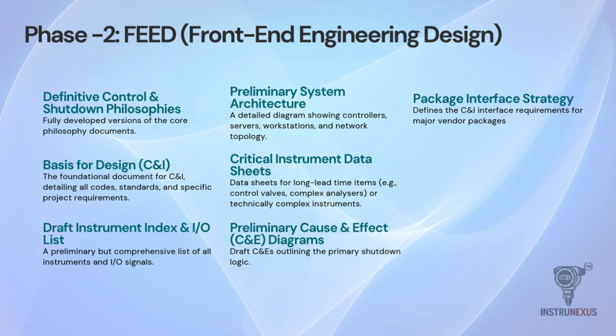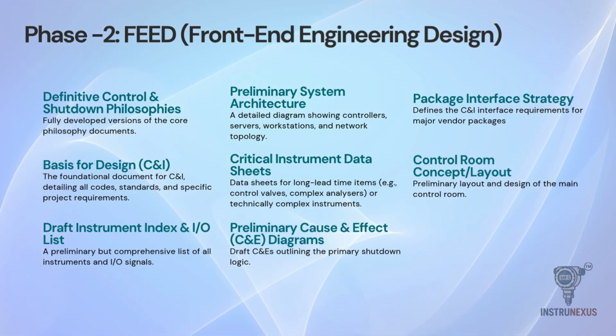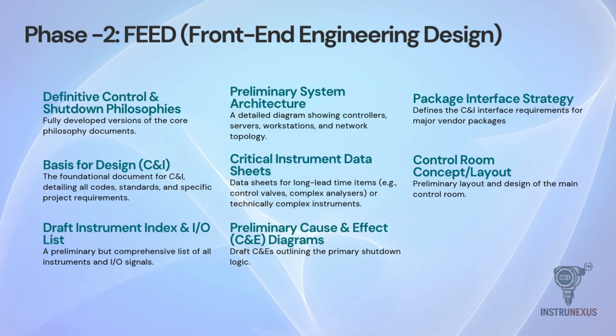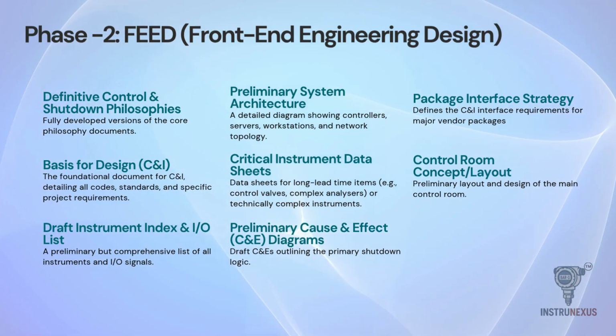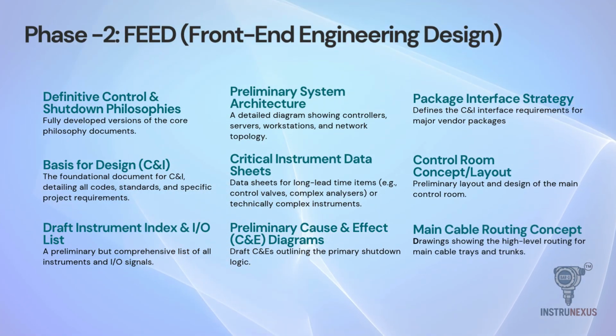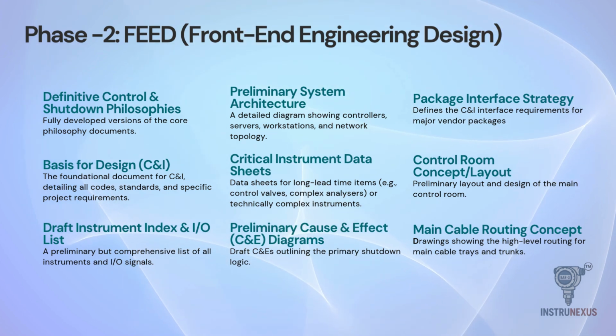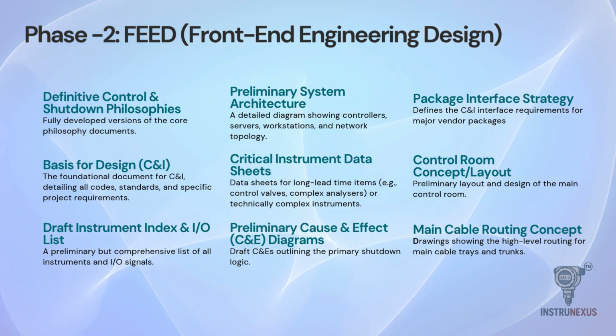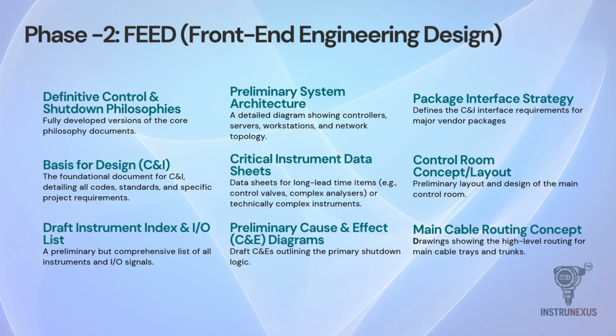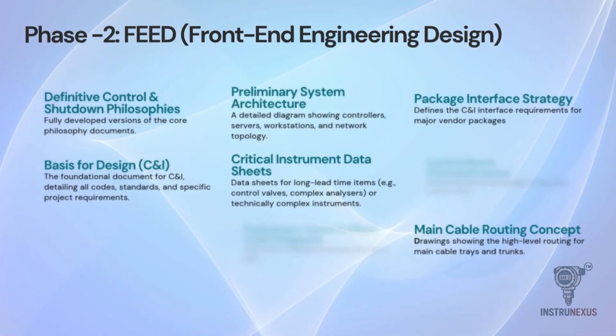On the physical design side, we produce the control room concept layout to visualize the operator environment, and the main cable routing concept, which shows the high-level paths for your main cable trays and trunks. These documents ensure that when we hit detailed design, we aren't guessing about space or logic.